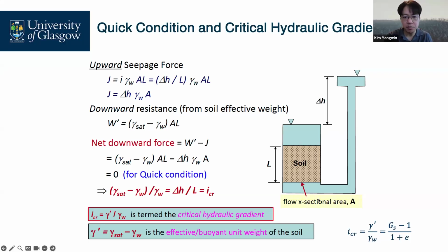This upward seepage force is the seepage pressure times volume. J is i gamma w times volume, that is, small j times A times L, which is the volume.